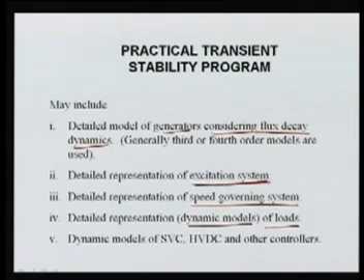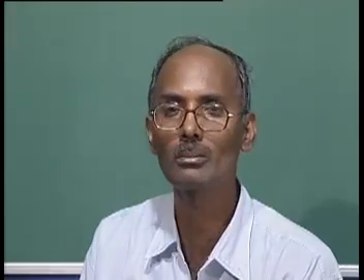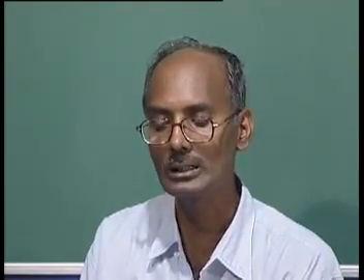Because there will be two types of loads. One may be static loads, another may be dynamic loads, such as motors. So the motor dynamics will also be included. If it is a static load, simply P and Q loads, then you can model it as static. But 80% of loads in a power system are induction motor loads, and that is dynamic in nature. So that dynamics should also be included in the practical transient stability programs.